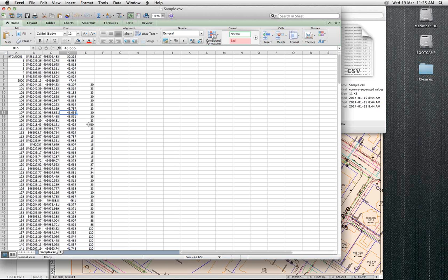Normally there will be a field which also has some plain English description of what's at that point. Top of wall, bottom of wall, IP, whatever it is that is relevant. In this case, I see repeated numbers, so I assume that there's some kind of legend that would go with this, and they have a kind of standard code that a 15 is such and such. So if I saw this in a job I was doing, I'd go and track that down from the surveyor. Okay.